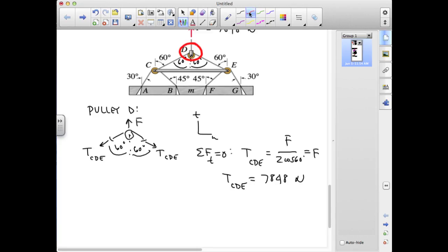Okay, so now once again our attention should be drawn to these pulleys because they represent the intersection of many different members. And one of the things you'll notice in this case is that we don't have the same angle between C and D and AC or CB. And so we no longer have this issue of the cable bisecting the angle below it because we've got another member which is now changing the equilibrium of the problem. So we'll once again follow our procedures and draw a free body diagram for pulley C.